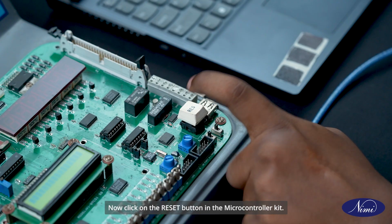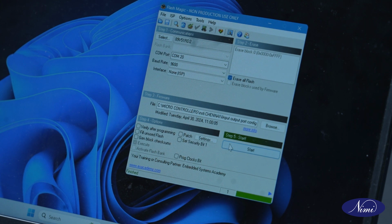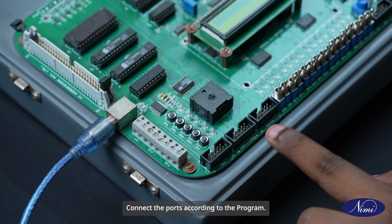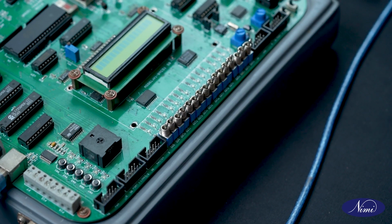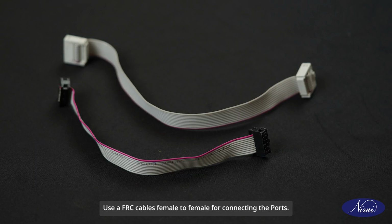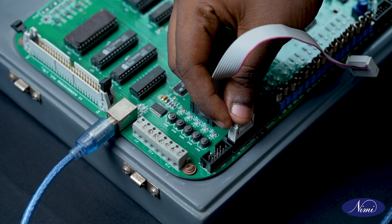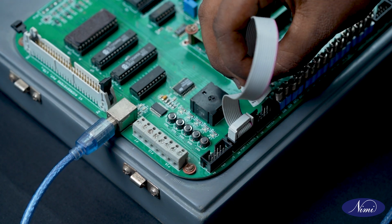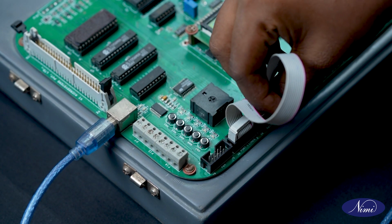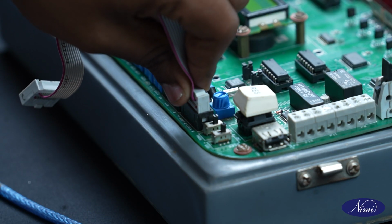Now click on the Reset button on the microcontroller kit to dump the program into the kit. Connect the ports according to the program. Locate the ports, switch and LED in the kit. Use FRC cables, female to female, for connecting the ports. Here, port 1 is connected to the switch and port 2 is connected to the LED.